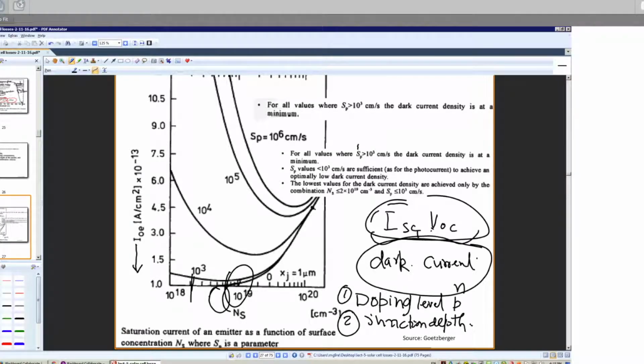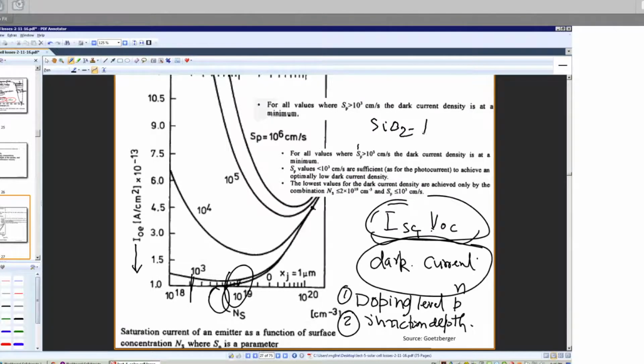But what we have learned, let me ask you, Dilip. You need to make a passivation layer. What information do you need to make a passivation layer? Thickness, right? What material I should use, how thick it needs to be, and also how I'm going to make that layer. Let's say SiO2 is the passivation layer. I gave you the material and the thickness, let's say 20 nanometers. Without that, you don't know where to go. You need this critical information.